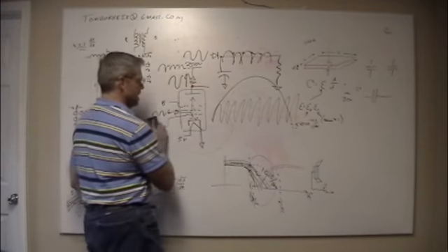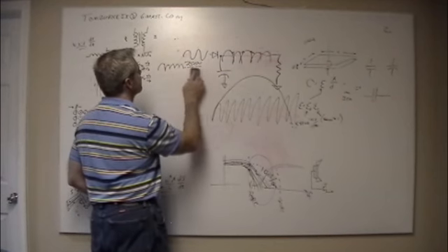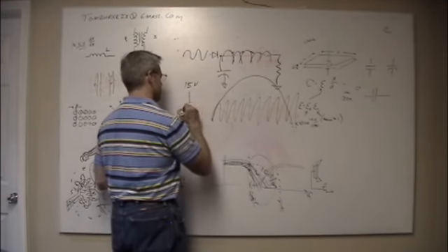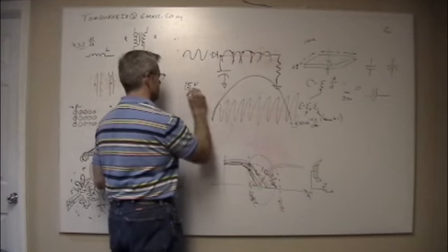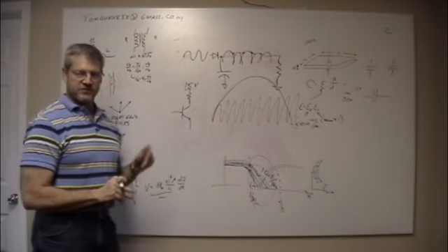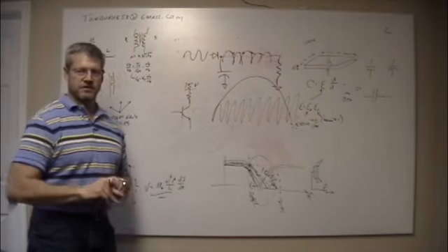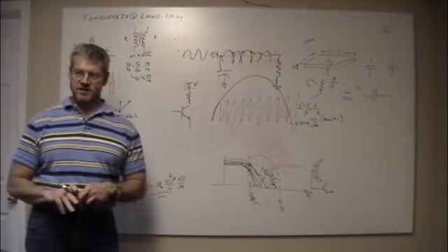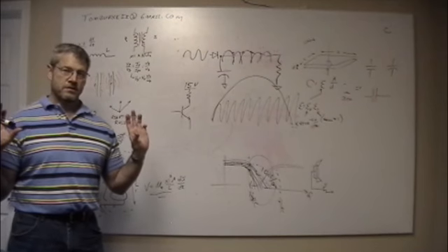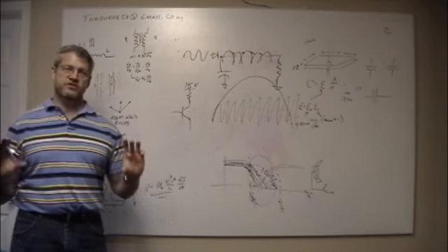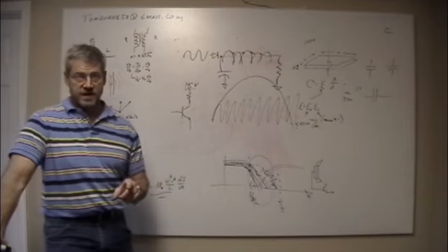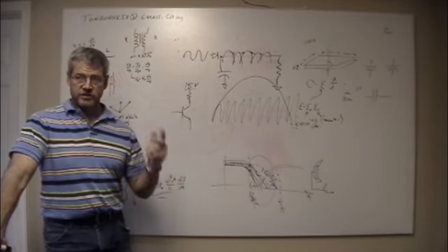So yeah, I could replace this whole block here with 5 volts or maybe 15 volts and a single BJT like that. That's got a lot of the same effect. A well-designed transistor amplifier is just as good, if not better, than a tube amplifier. The difference is, on a good transistor amplifier and an equally good tube amplifier, it is much easier to build a transistor amplifier of better quality. A transistor amplifier will almost nearly always have better phase noise, better harmonic distortion, and total harmonic distortion.